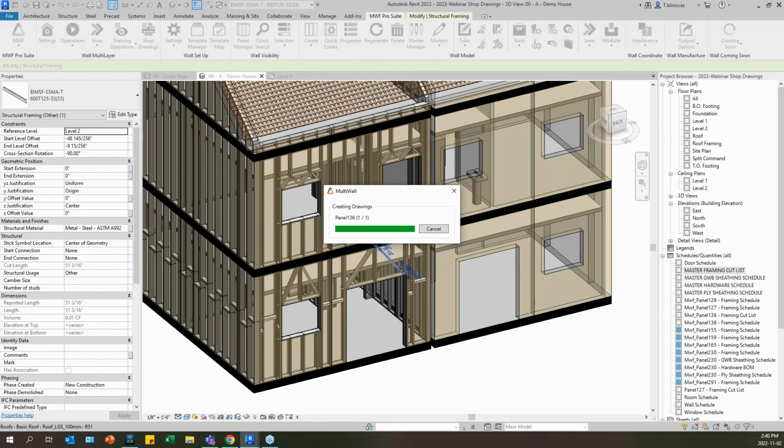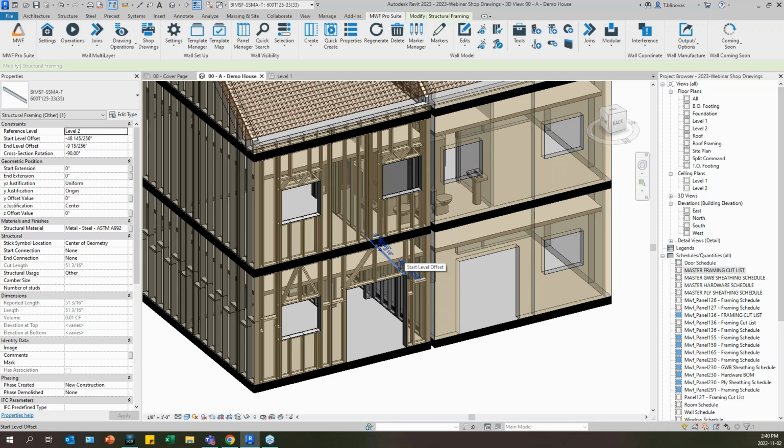So at this point, if you get any errors, chances are that it could be maybe the path that you need to set up for the sheet layout. Sometimes if you have some parameters that are not existing in that specific panel, you're going to get some warnings as well. Usually when the error is related to parameters missing or dimension style missing, the drawing will still get generated. It's just that that particular parameter or dimension style will not be in the drawing.